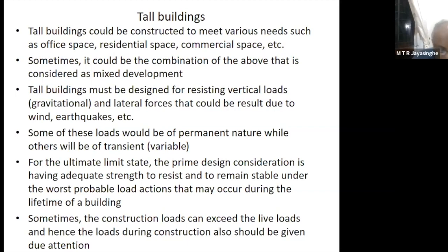So now you can see, when you look at all these good properties, you make a good quality concrete using fly ash, good quality cement, and then you use super plasticizers, use less water, you can make dense, flowable concrete, and you'll end up with a good quality concrete in the slab.